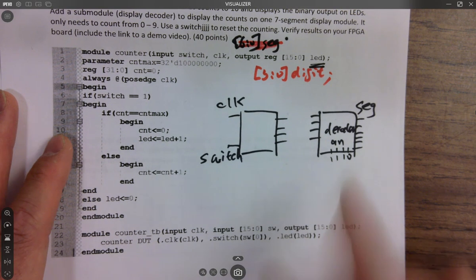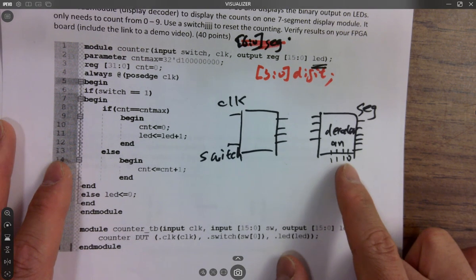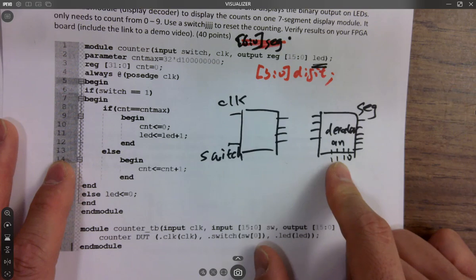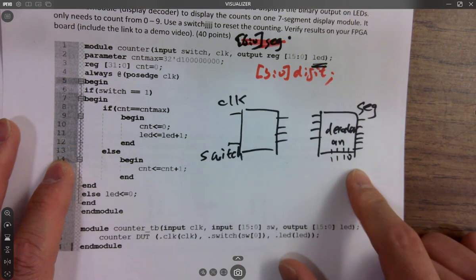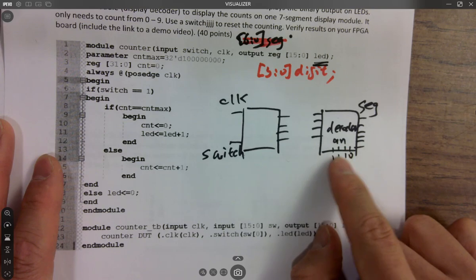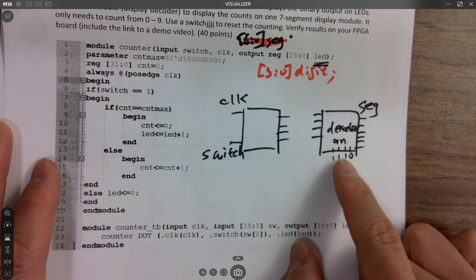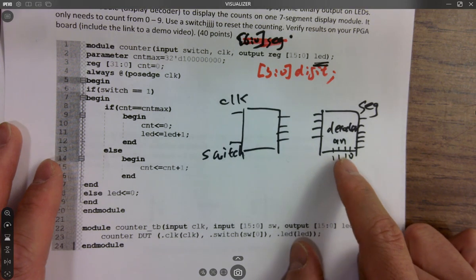Just directly throw these values to it. You can imagine it's going to pull these 3 pins up to VDD and pull this down to ground. These are just wires, so they're not changing. You don't need anything in the middle to change it. But whenever you have to change it, like the ones we use for the lab, where we are even shifting it and doing all these kinds of operations, you need an intermediate register for this one.